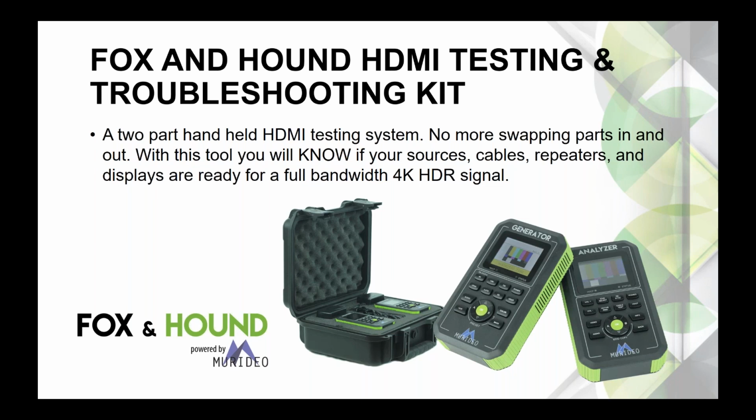And then on the analyzer side, so this one goes at the head end or replaces the source, and this one goes where the TV would be. On the analyzer side, we can actually get the video coming from the generator or from the source. We can also store a couple EDIDs in the A and B buttons. We can store a couple formats in the A and B on the generator, but we can emulate an HDCP 2.2 TV, a 1.4 TV.